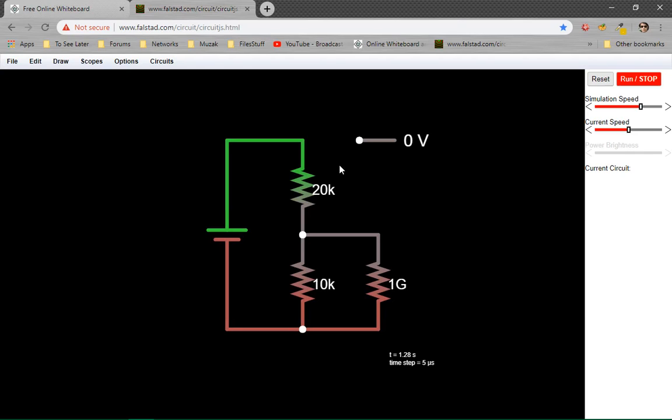Nature produces a lot of electric fields, so do other circuits and machinery. For example, doing circuits near a computer, we might expect our circuit to pick up signals from the computer. So we can't use too high of resistors, or the power going through them is so low that we can't distinguish it from the noise we are picking up.